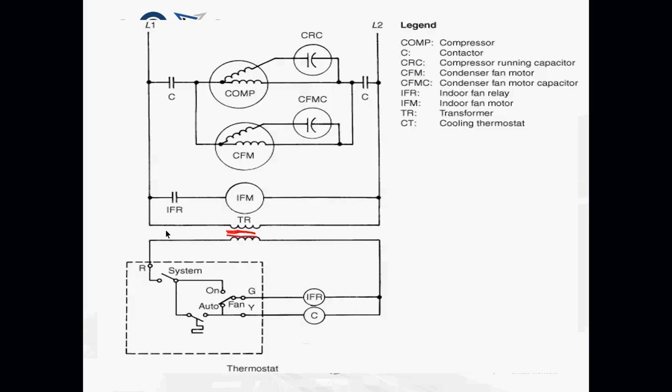We're providing power to the transformer because this side is my primary, which is the load side, and by the way, L1 and L2, what voltages are we talking about the minute we go to L1 and L2? Are we still talking about 120 volts? 240. Yeah, we're in the 240, 208. We're no longer in 120 volts because I now have two lines. I no longer have a neutral here. We've actually had a lot of schematics come up through this course where L1 and L2 was meant to depict 120 volts and not 240 like you would think.